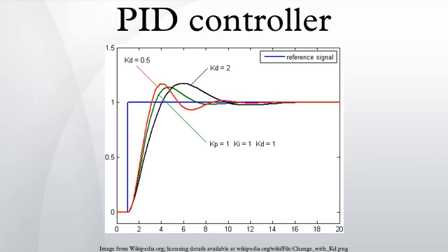Cascade control. One distinctive advantage of PID controllers is that two PID controllers can be used together to yield better dynamic performance. This is called Cascaded PID Control. In Cascade Control there are two PIDs arranged with one PID controlling the set point of another. A PID controller acts as outer loop controller, which controls the primary physical parameter, such as fluid level or velocity.